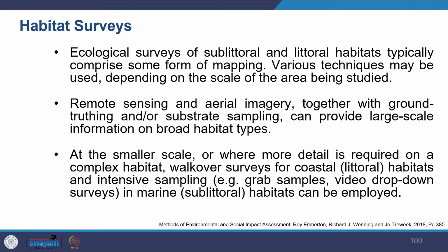You would undertake mapping of these areas, and there are various techniques that can be used, depending on what scale you are looking at. The most commonly suggested one is remote sensing and aerial imagery, and that would require ground truthing, which means you have to do field investigation.